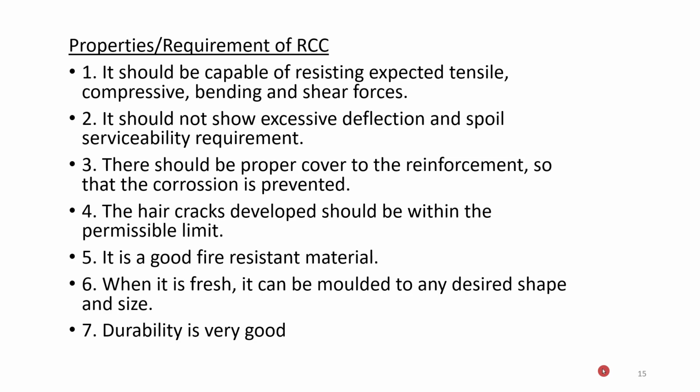To lessen that, we provide the required steel bar. And we should provide proper cover to reinforcement. Cover is the distance between the external surface of concrete and the steel periphery.